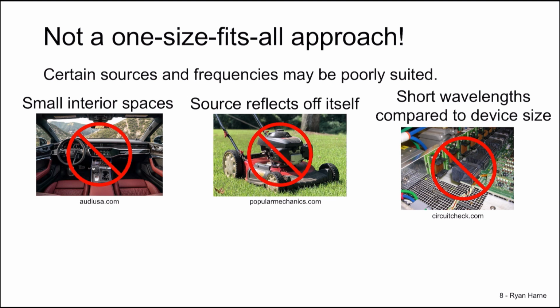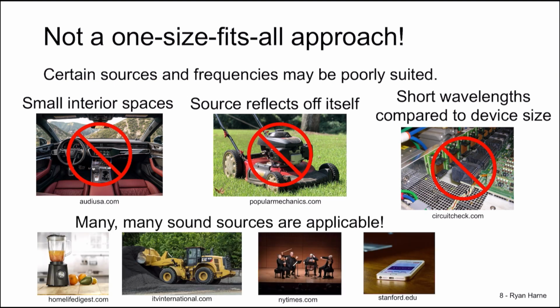On the other hand, this modeling approach is quite helpful for many sound sources. It depends on meeting the multiple criteria, understanding whether we're in the near or far field, and appropriately discretizing the source to make sure we're small with respect to the wavelength, and our distance between the discretized point sources is also much smaller than the wavelength.